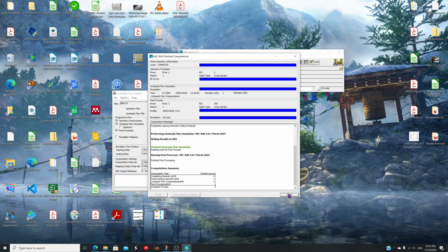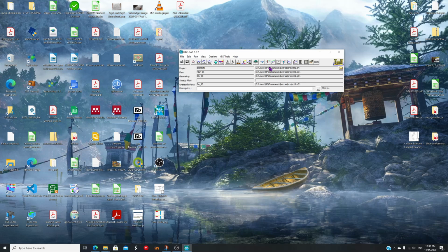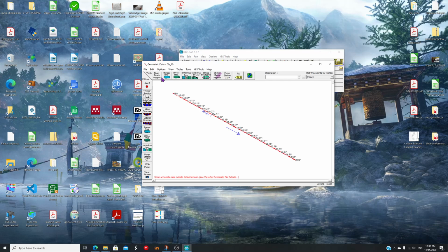But the model did not go well, because you can see this dip in the rating curve, which means there was fluctuation. So this is not a very stable model, so we have to do something to fix some errors. I mean, the cross section that we created at 1000 maybe was too large for the computer to solve, and that's why it's creating some mess. But anyway, this is how we do the analysis.